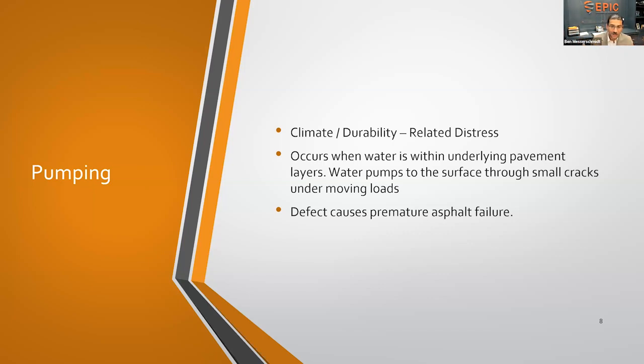Now, building it on the outside on a firm footing, firm ground is really what you want to do. So you can imagine over time, really having that presence of moisture or water within those pavement layers is only going to cause premature failures within that system. It's not going to live up to its full life expectancy, and you will be having to do some large scale repairs if it is left unaddressed. And that could be addressed in a variety of different ways. If it's going to be a water table based issue, or if it's going to be a surface runoff based issue, those are going to be handled in two different ways by your engineer.